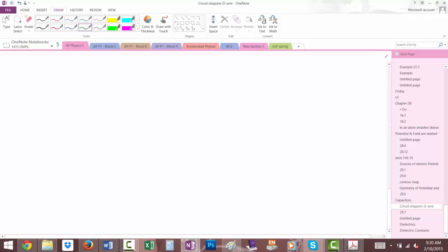So, why do you want to do that? Because sometimes you need a certain capacitance for a project, for a certain specification. We need a capacitance of 17 farads, 17 picofarads, whatever. Maybe you can't go to the store or order online a 17 picofarad capacitor, but you can get a 15 and a 10 and a 5. How can I arrange them so I can get what I need? That's what we're talking about.